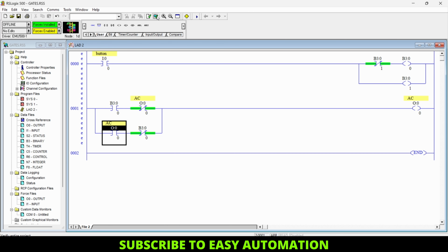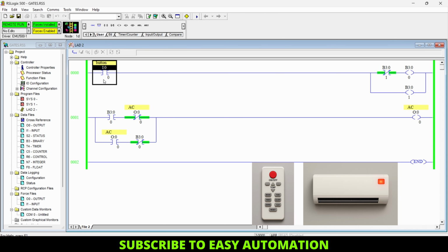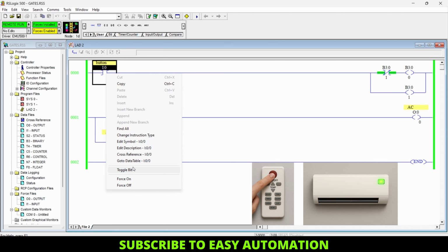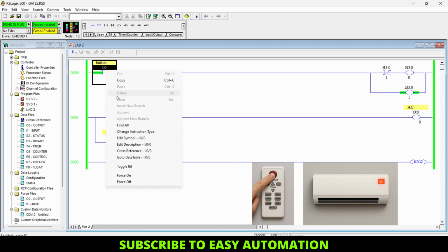So let's verify. Now our program is in idle condition where our inputs and outputs are at their idle condition, like these NO contacts are NO and NC contacts are NC. Let's imagine this button as your AC remote's button. Now I will press this button and our AC is on, and if I release this button, our AC is still on. But if I want to turn off this AC with that same button, then I need to press this again and release it.